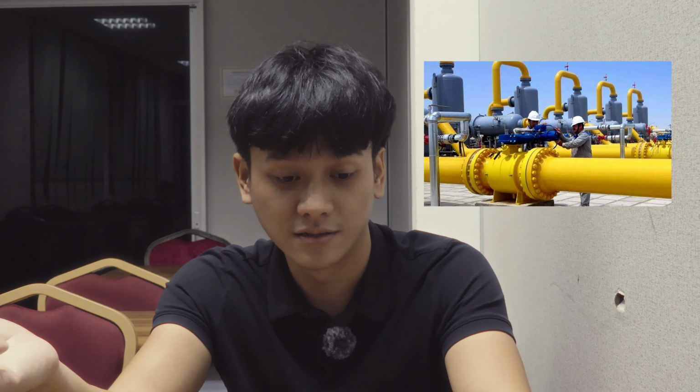Before introducing the well fluid, several checks are carried out to ensure the separator is safe to operate. The operator will check that all valves are in the correct position, ensure the pressure relief valve is operational, then verify that level, pressure, and temperature instruments are functioning. Drain any remaining liquid if necessary.